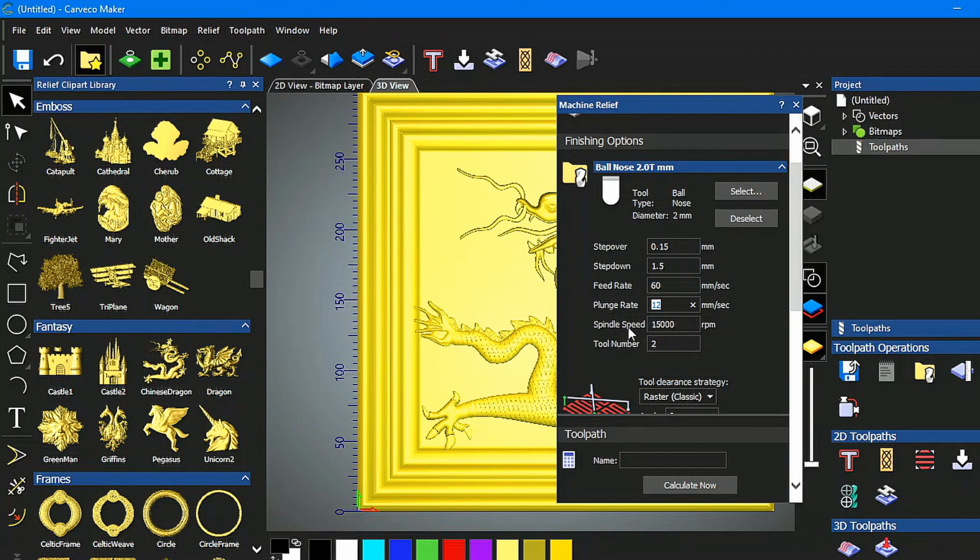I normally do 50%, which is 30 millimeters, because when you're traveling along here with the cutter, it's like going up and down over mountains and ridges and what have you. So it's not 60 millimeters in a straight line. In this area from here to here, yes, it would be. But the machine will hold up, lift the tool, then move forward, then drop the tool, then go up to full speed, then stop again, you get the idea. So if your machine is able to operate quite quickly or cut quite quickly, these are fairly realistic.